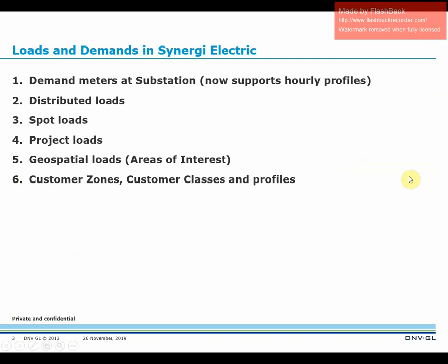So demands are on the feeder meter typically, and recently we've added the option to support hourly profiles. So if you have hourly data coming in from your substation, either from Pi or other systems, we can load those in and create hourly profiles on the substation feeder meter. Otherwise, many of our clients just simply use the peak hour.